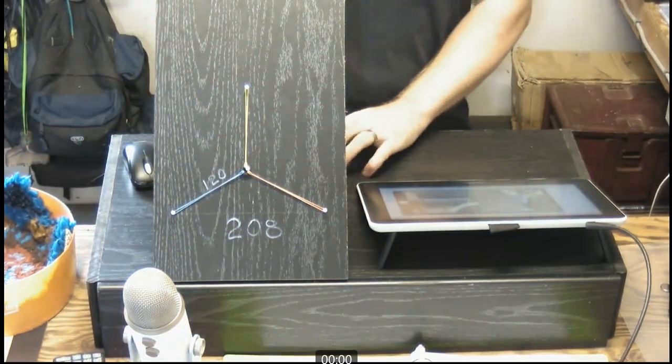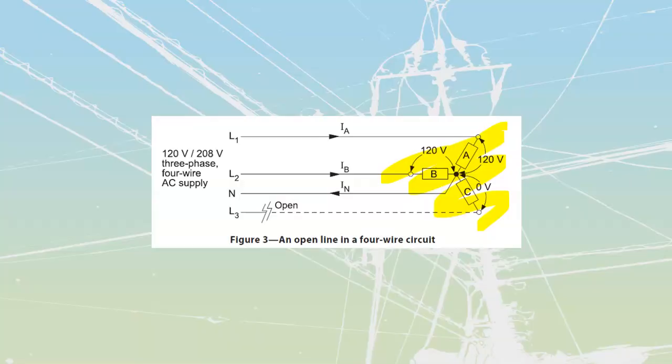Okay, going back now into our drawings over here. We have got these same ones that we have to look at, the exact same ones that we had there before, and we are going to use the exact same resistances, 10 ohms over top of here, 10 ohms inside of here. And we saw that we lost this line over here, but because we have that neutral, that anchor point inside of our circuit, we're still going to maintain the same 120 volts over top of these. So I can figure out my phase values of currents.